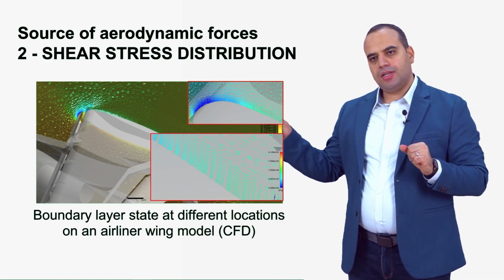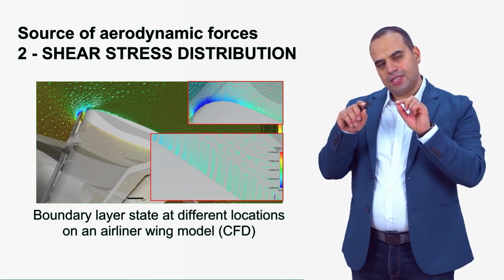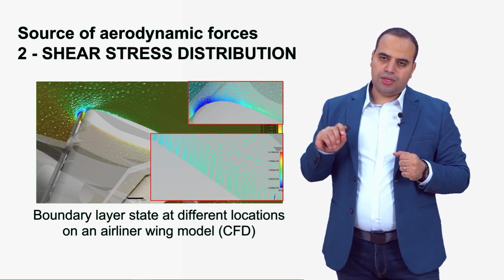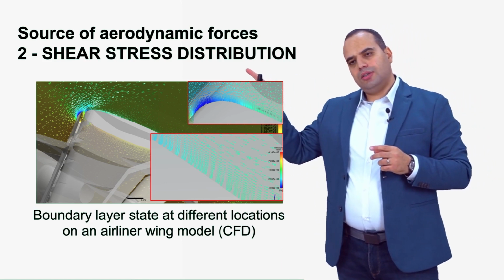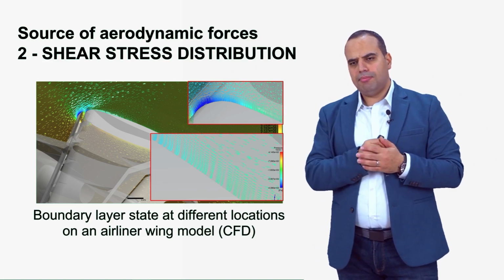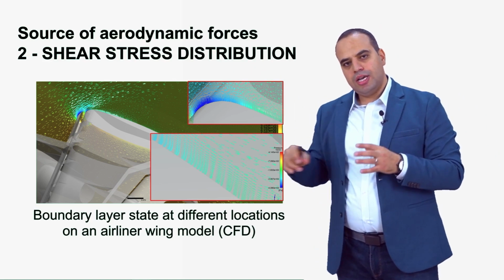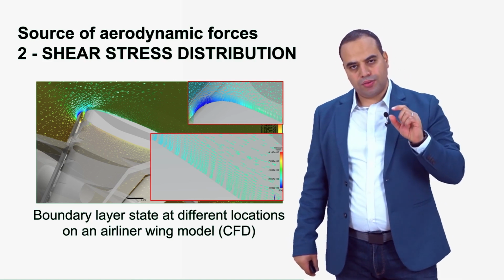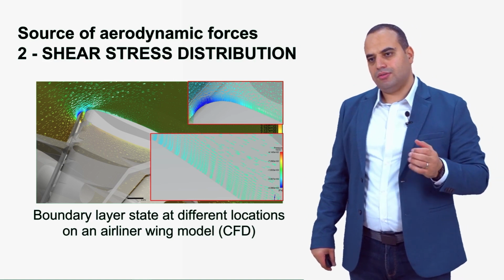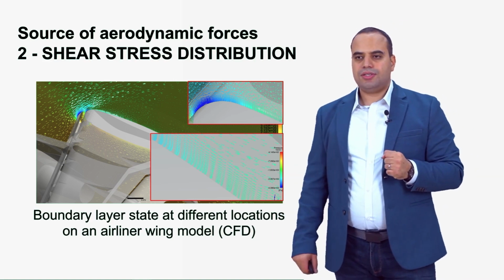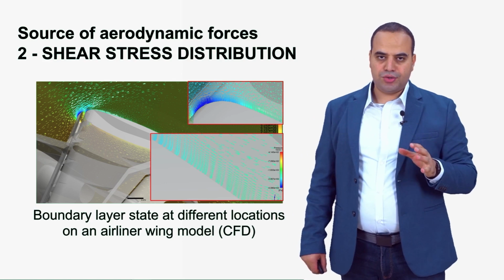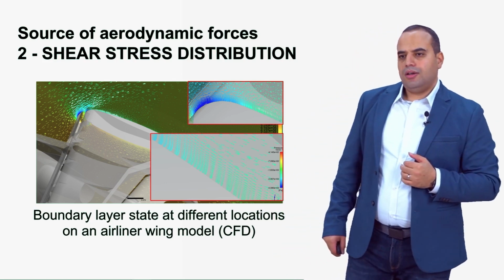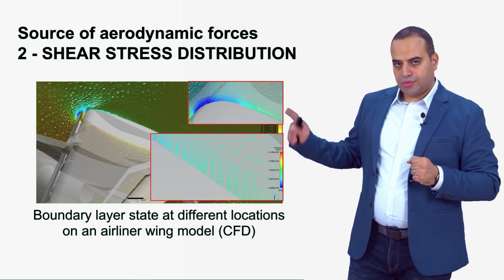Now we can see that unfortunately we don't have the legend that talks about the size, but indeed you can see how we can zoom. We are zooming, in fact, into the nose of the airfoil. This is the blue color, low pressure, on the nose of the airfoil. It is zoomed on the upper part here, and it is zoomed a little bit below. So it is a very tiny layer on the surface of the wing, right? It is like 0.01 millimeter or even smaller than that. This tiny layer is what is causing the friction drag, which is a very large force if we integrate over the entire surface of the aircraft, which can be, for example, a few tens of square meters. So it's quite a very large force.